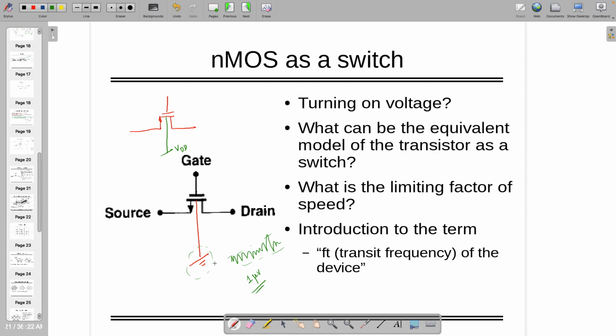So noise is an input, and at that time, if the circuit is an amplifier, and the gain is 10 raised to 6, this will reach directly to VDD, right? So you have to understand the severity as you are going for higher gain. Not 100 dB, anything is possible in 180 nanometer and any technology, right? So it's not true that you can't achieve a certain gain or frequency.